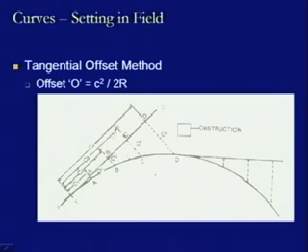So, once we compute this value, say if instead of C we put C1, we will get the offset which will be measured from A to this point A dash, and this is the value here. Similarly, if we put the value as C2 as a chord, then we will get O2B. So, this is O2B, this is B, and this is termed as O2. Similarly, this is O3 or this is O4 and likewise.